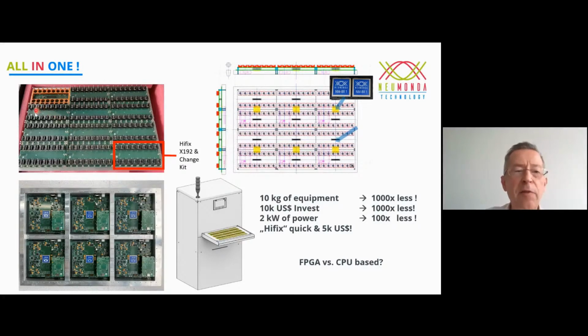And it rebuilds the application. It's not so clean in signal integrity like a tester because it more rebuilds the memory channel on a motherboard, even a little bit poorer because the distances are longer because of the DRAM sockets, but that is good. That provides guard banding. That makes it signal integrity poorer and more rebuilds a customer environment.